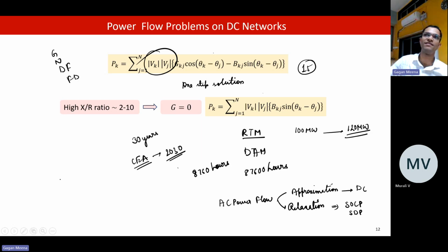If we don't have that much budget, we reduce some; we'll have only one or two generators. For the next 5 years, they can plan, and how to plan those 30 years we also need to see. Next 5 years, I will do this; after that, I can revise. I can use the relaxed versions, or AC power flow for 1 year. Because construction of a coal generator requires several years, 5, 6, 7 years, for at least a 10-year planning horizon, I need to plan 10 years ahead. 10 years is also a very big framework.